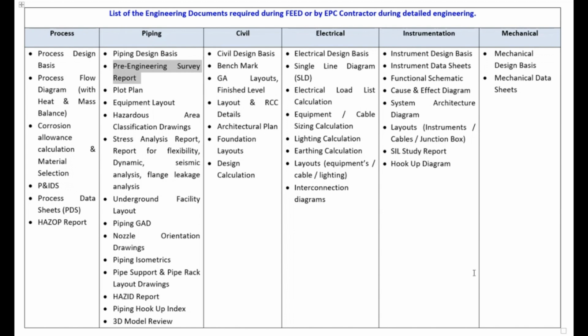Similarly, all the disciplines will develop their design basis documents. If you see here, civil design basis, electrical design basis, instrumentation design basis, mechanical design basis. This is nothing but the design concept, how the engineering will flow from the point of view of each discipline.